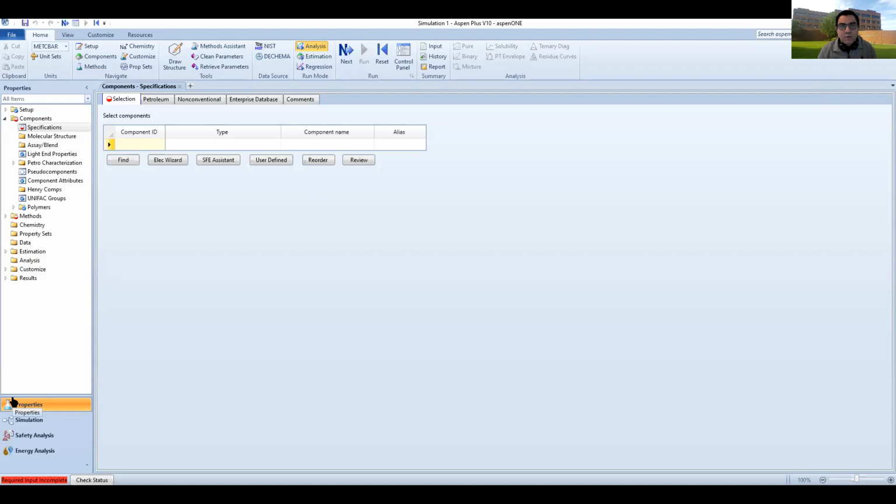Then I move on to simulation, where I start doing more of the chemical engineering stuff, such as dropping my units, mass balances, my streams, temperatures, and pressures of operation, etc. This is similar to what we talked about in process design: start off by creating your database of all your chemicals, and then you start moving on to building your base case.